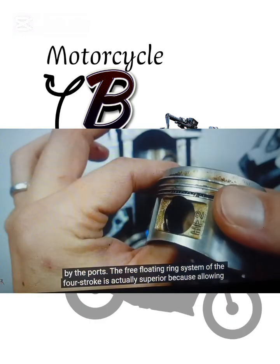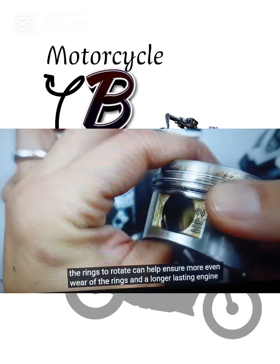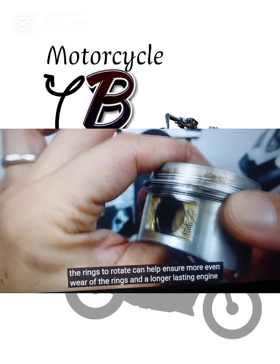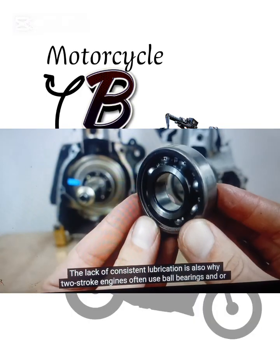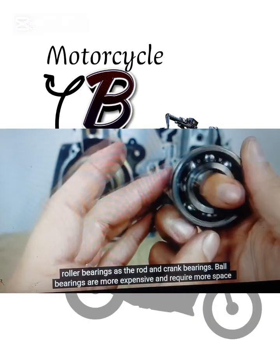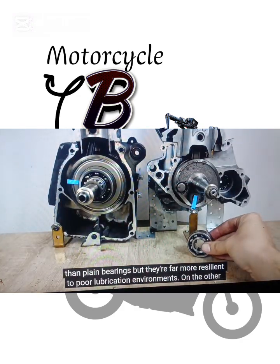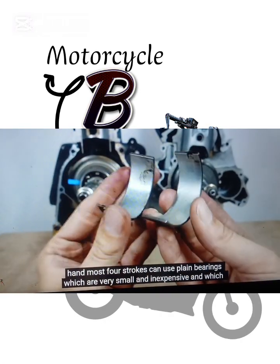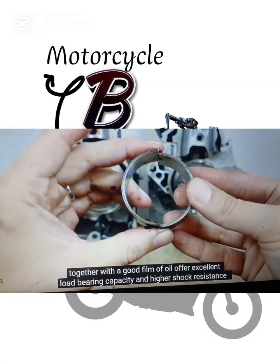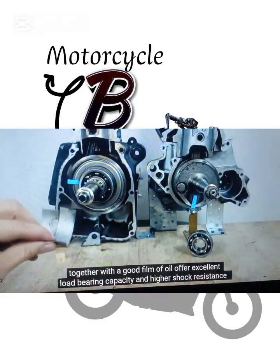The free-floating ring system of the four-stroke is actually superior because allowing the rings to rotate can help ensure more even wear of the rings and a longer-lasting engine. The lack of consistent lubrication is also why two-stroke engines often use ball bearings and/or roller bearings as their rod and crank bearings. Ball bearings are more expensive and require more space than plain bearings, but they're far more resilient to poor lubrication environments. On the other hand, most four-strokes can use plain bearings, which are very small and inexpensive and which, together with a good film of oil, offer excellent load bearing capacity and higher shock resistance.